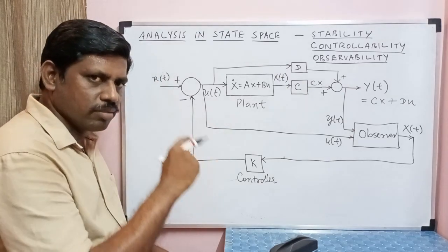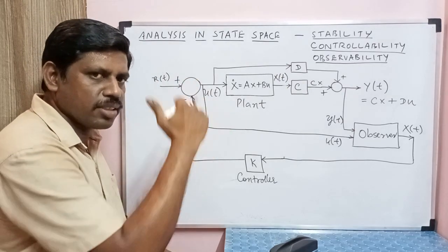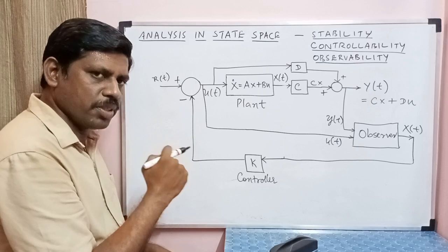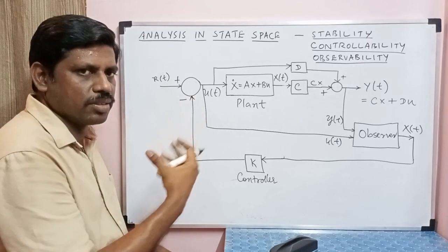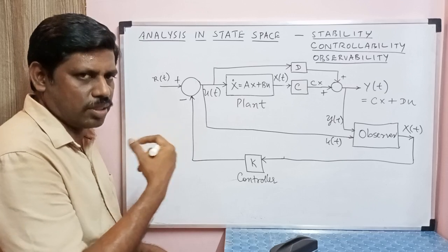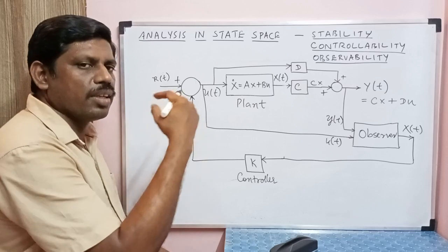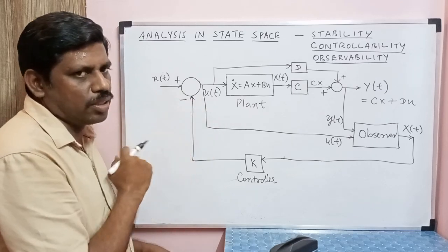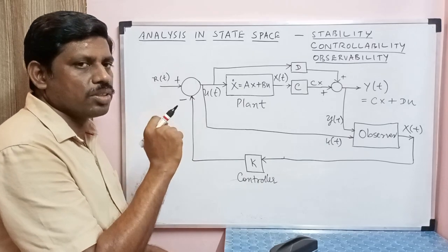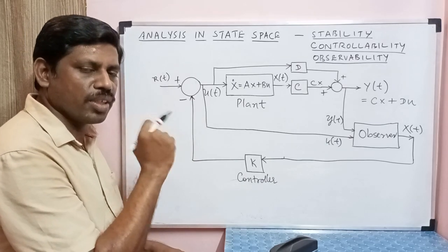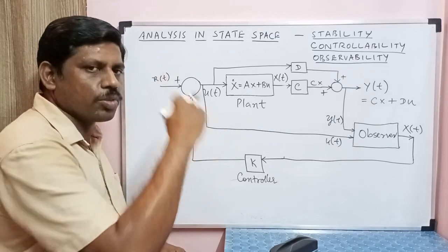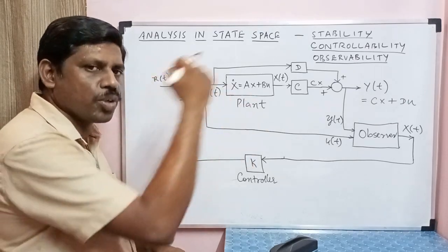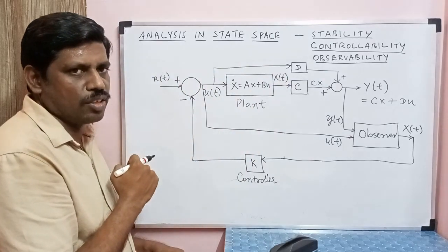But what about the rotor position inside the BLDC motor? It can also be measured, but you need a lot of provisions, and it is a bit complicated to measure the rotor position inside the BLDC motor. But this rotor position is a very important quantity in control of the BLDC motor, because the rotor position has to be sensed and the appropriate circuit has to be switched on.